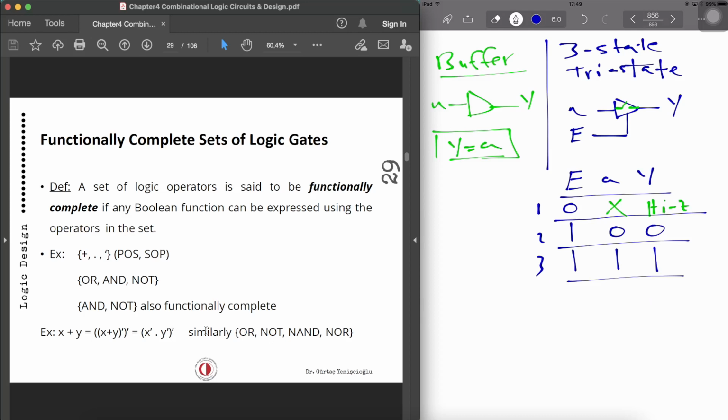So with these equations, we are ending up with an equation which is giving us a solution to that element of that set. Now, we also consider the NAND and NOR implementations, which we have said are universal because we can use NAND and NOR gates to implement any gate: inverter, AND gate, OR gate, and the same applies for the NOR gate when you can implement an inverter, AND gate, and OR gate.